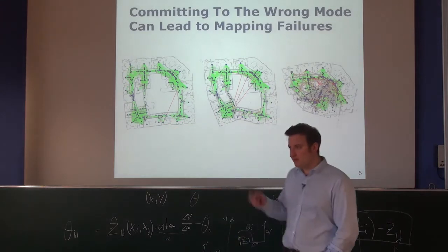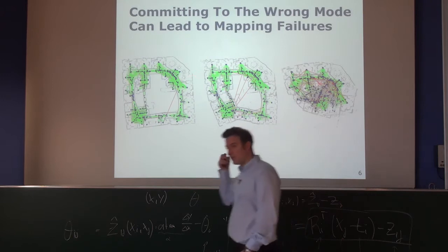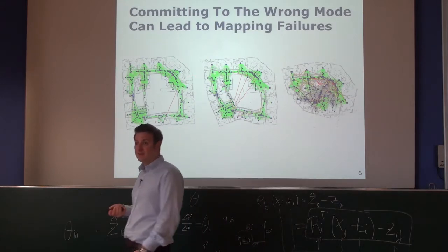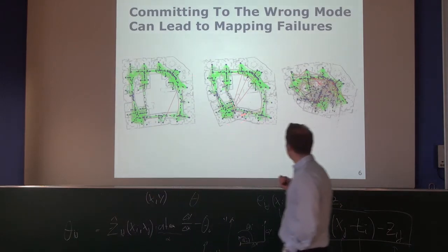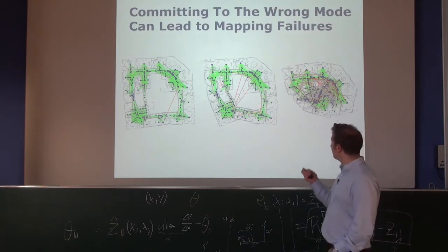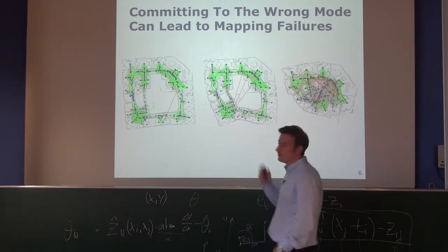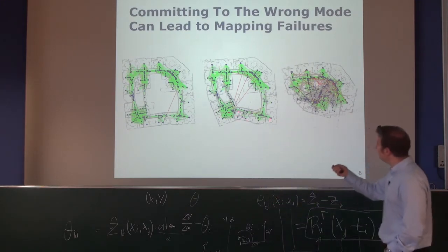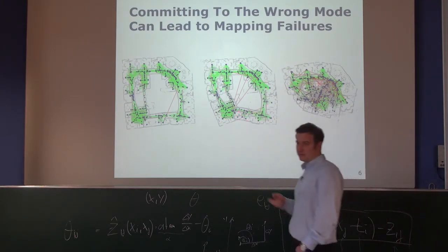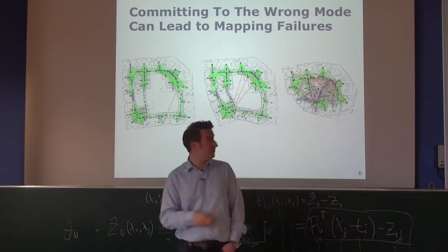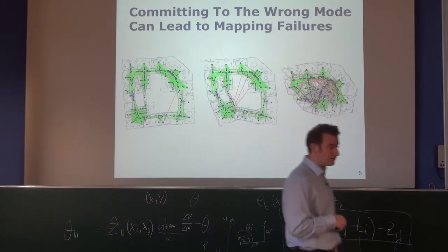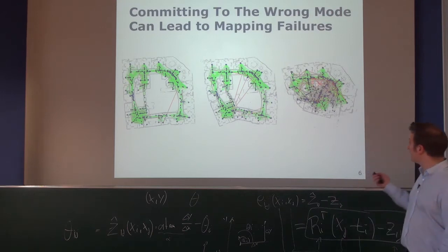The least squares error minimization, where the error is a squared error term, actually tries to minimize that. If we add, I think there were 10 wrong constraints, the map gets so distorted that it's unusable for navigation, at least down here. Here you still may be able to navigate with an autonomous system. But if you have 100 constraints, you end up in situations like this.